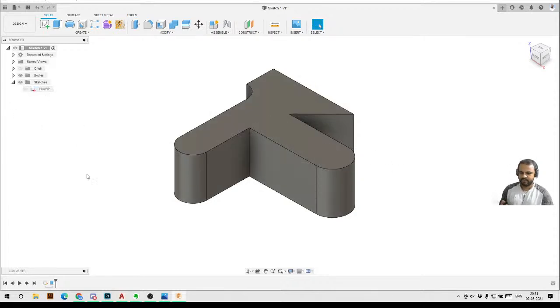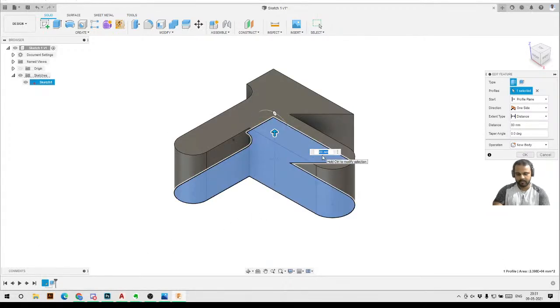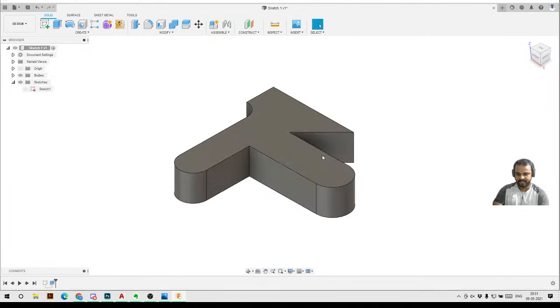Here you can also see we had activated our design history. In the design history we get the record that first we created this sketch, that is sketch 1, and then we extruded that sketch to give it a 3D shape, 3D height. So at any time if you want to change the height of this 3D model, go to your design history, and let's say we created this extrude option to give the height, just double click on that, and again you will be able to make changes like this. I can change the height and press enter, so the things will update quickly, right?